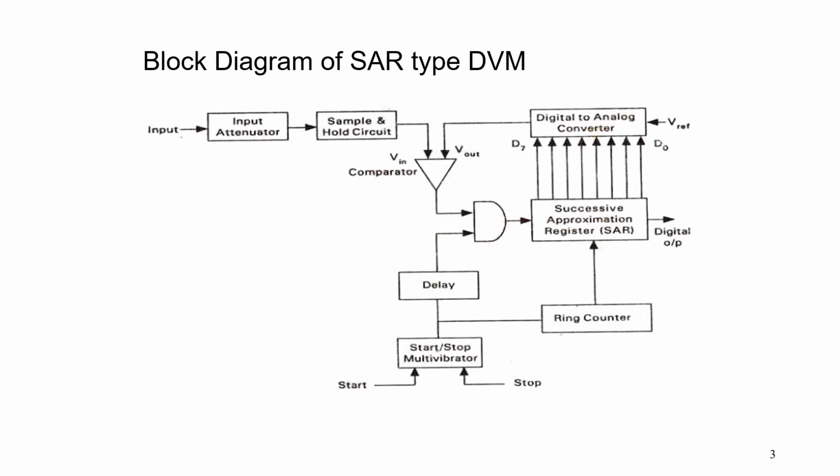This sets 1 in the most significant bit of the control register and zeros in all other bits down to the least significant. When the control register is an 8-bit register, its reading would be 1 followed by 7 zeros.